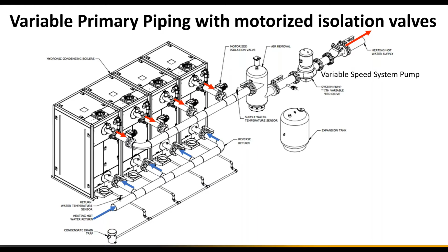During low demand, low flow conditions, we may have 1 boiler operating, but as we now have high turndown boilers, we can easily maintain the load with 2 boilers running at 15 to 20%. In that case we operate through 2 boilers, and as we go into the colder days of the year, or the system comes out of night setback and certain zones kick on, the variable speed pump will ramp up its velocity, and depending on the control system, the boilers will bring on number 3 and number 4 as needed. But overall, we're really trying to achieve and maintain the heating load by operating the boilers at as low a firing rate as possible.